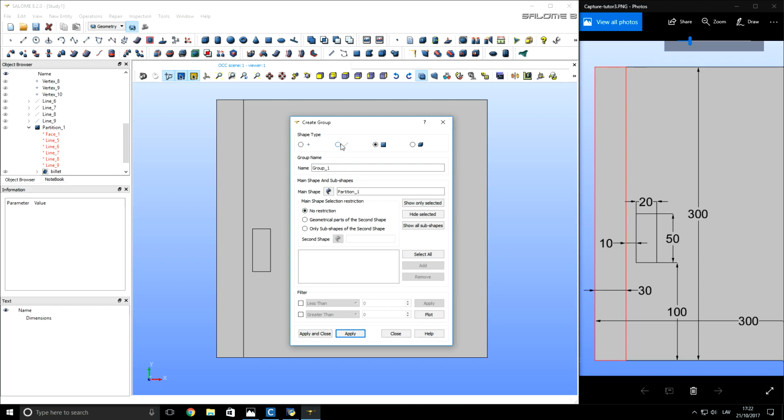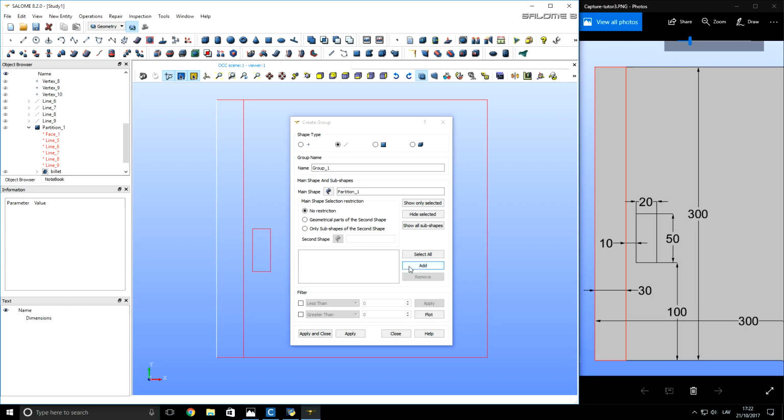Now we want to create boundary conditions. Thereby we will use this edge tool here, edge shape type for edges. First we will select this axis for billet. I will click add and name it billet axis. Next, we want to create those two surfaces, boundaries here for billet that are outer boundaries.